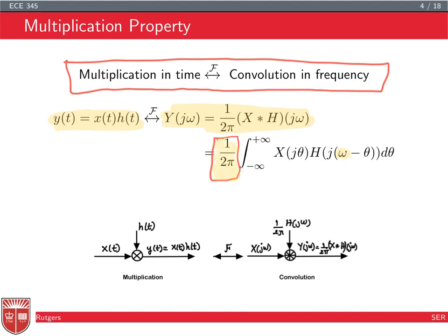Now you may think, why do I care about multiplication in the time domain? Well, we just saw an example in the previous lecture where you want to do modulation by the carrier frequency to shift the frequency of your signal, whether it's audio or video, to a frequency that you can transmit, which may be dictated by standards, such as for your TV if you're receiving cable, or wireless video, wireless 3G or 4G or any wireless system.